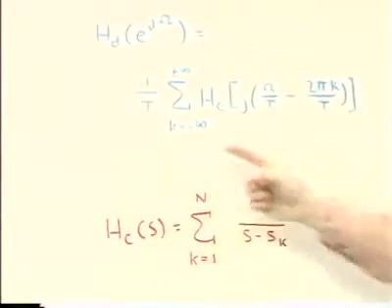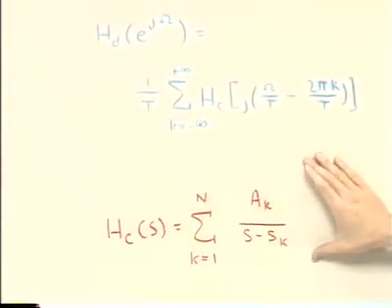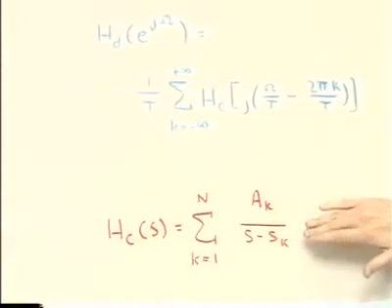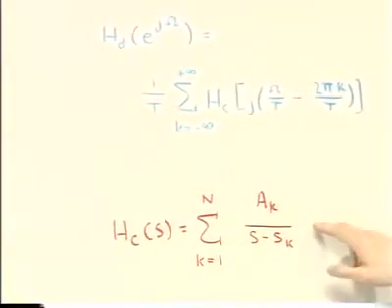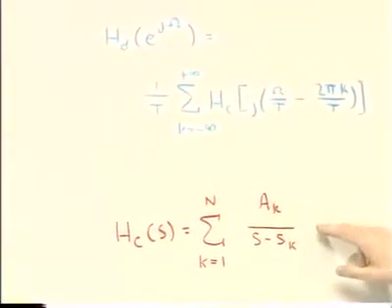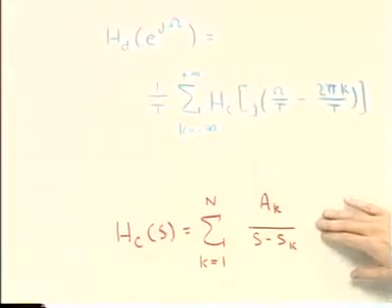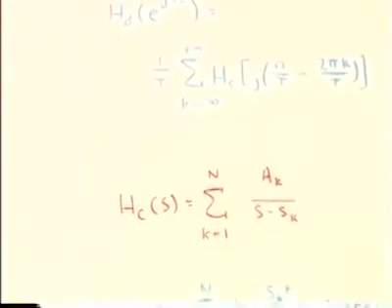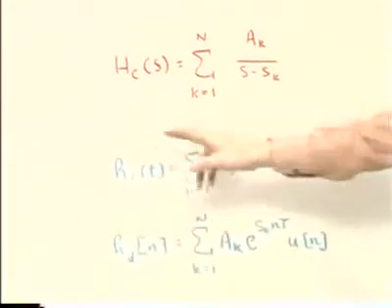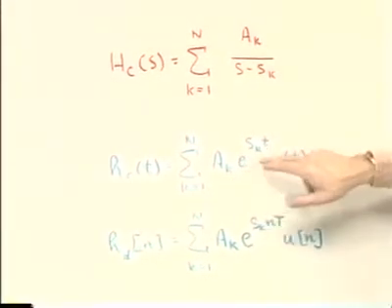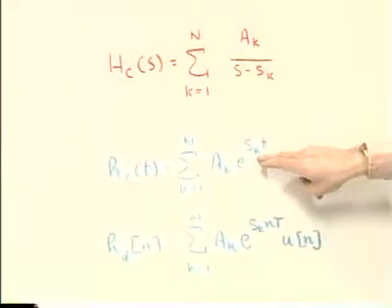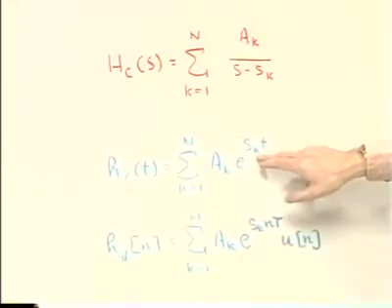If we expand this in a partial fraction expansion, and we look at the impulse response associated with this, we know how to take the inverse Laplace transform of this, where I'm just naturally assuming causality throughout the discussion. The continuous time impulse response, then, is a sum of exponentials with these amplitudes and at these complex exponential frequencies.